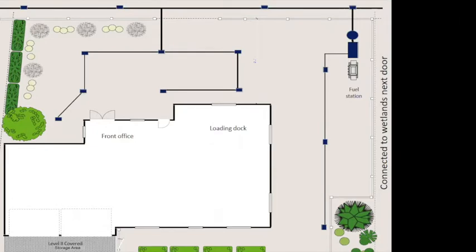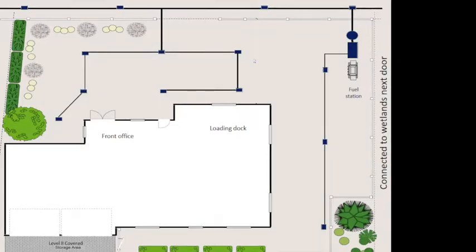So let's look at the run-on from the auto storage yard. They could potentially have all sorts of automotive fluids. So maybe putting a cement berm along the backside of your business to keep run-on from coming onto it, and diverting it, or keeping it on the auto storage yard side.